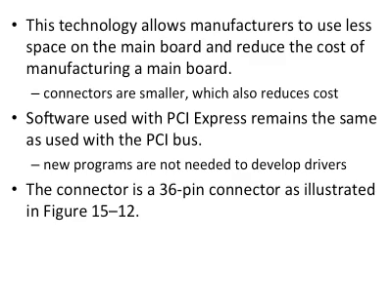But on the other hand, as we said earlier, we want to keep the benefit of the plug and play feature. So the PCI Express bus still supports the PCI configuration space. The first 64 bytes are organized the same way. It has the vendor ID, device ID, class ID, etc. It also has those BAR registers to allocate addresses for resources available on the device.